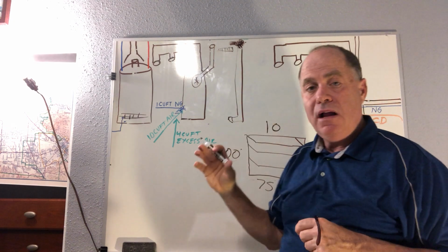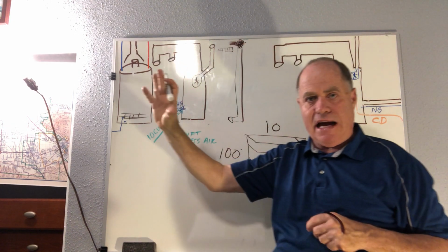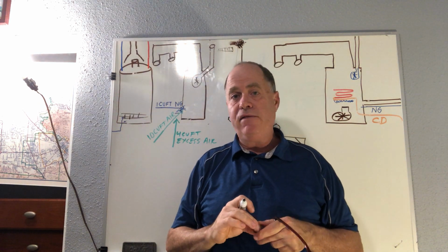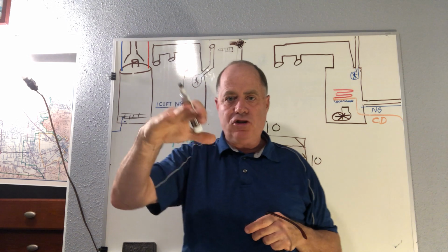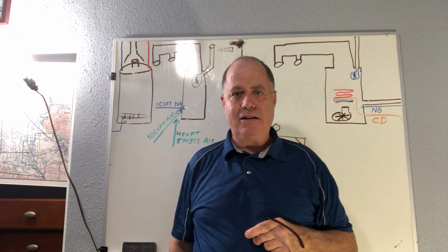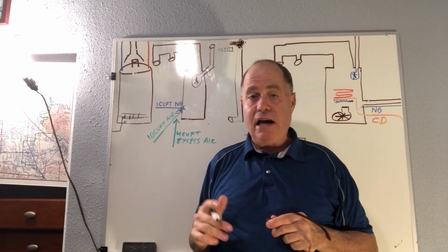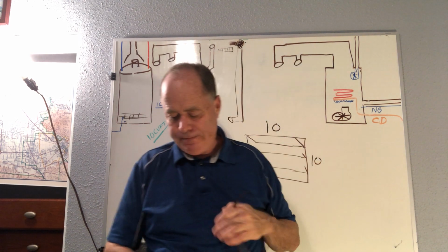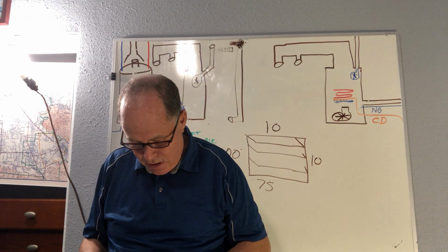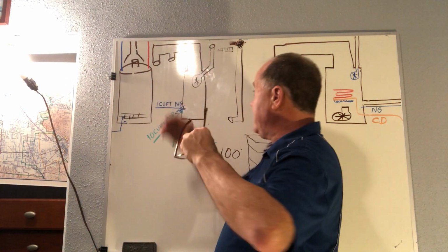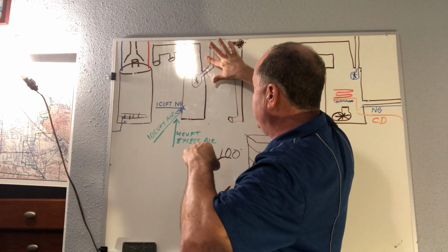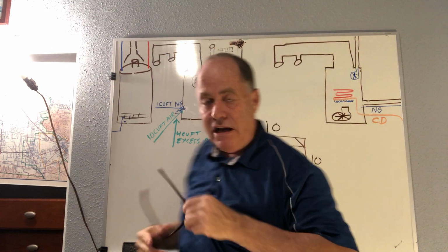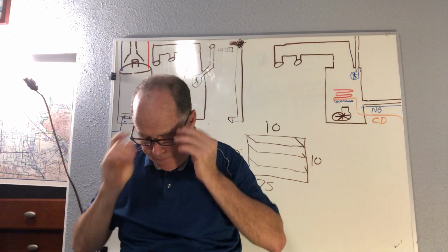Okay, and again, you have these vents and screens all over your attic, around the outside of your house. If you ever get insulation blown in, before they leave, walk the perimeter of the building and make sure that those vents aren't blocked in your attic, and have them take a rake and tamp it down or move that around a little bit, okay? And you cannot have manually operated dampers where somebody can just close off one of these vent pipes, okay? You can't have anything like that. No manually operated dampers, okay?